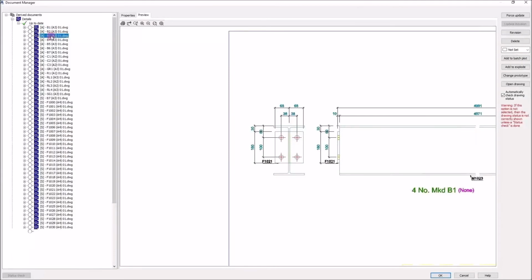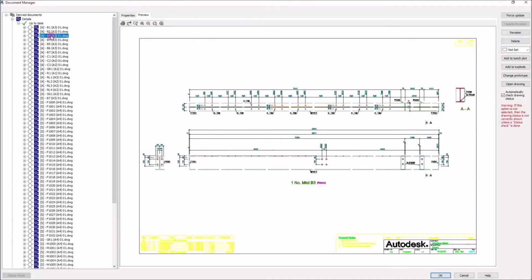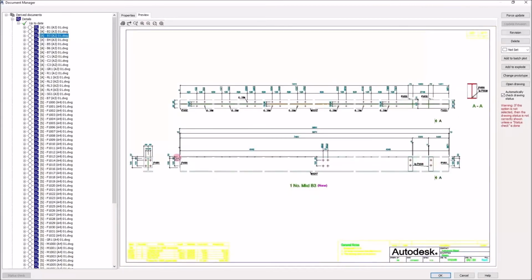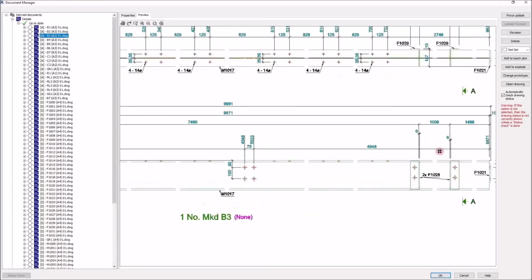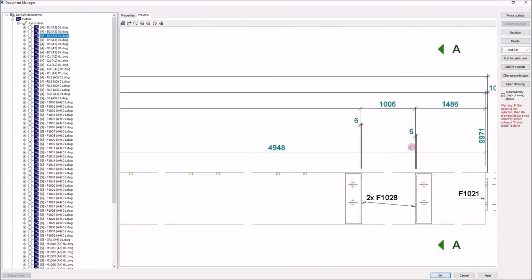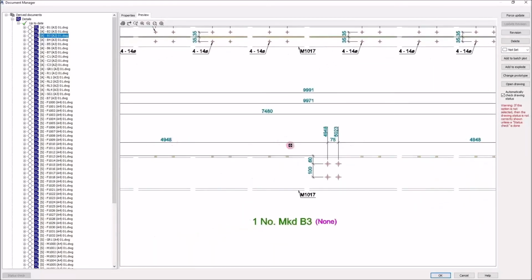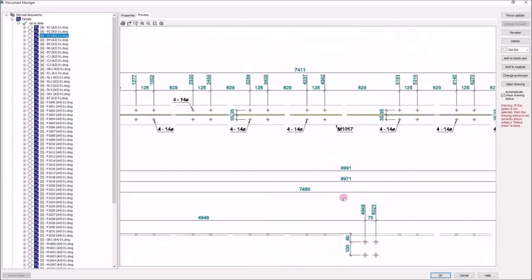We'll see if we can show a couple of drawings if they've got a bit more information in there. There's quite a good one. There's one with holes in and some little fin plates as well. So you'll get a front view, again with the overall information. Then the system will start to locate these welded pieces that we have on there. Any holes that we have on there, the system will give the dimension between the holes, but it will also give an overall running dimension.